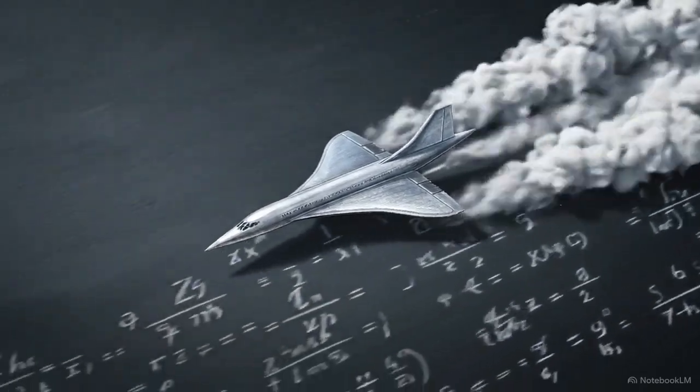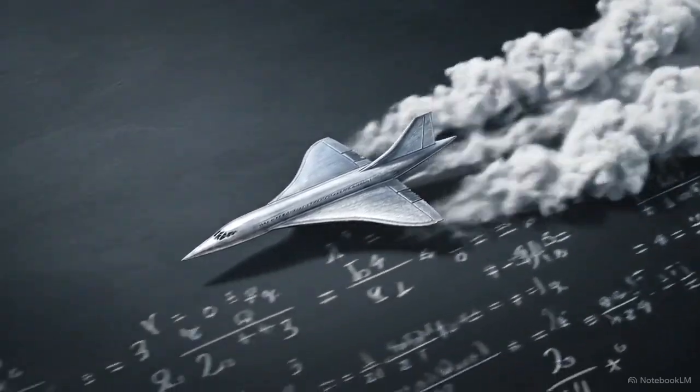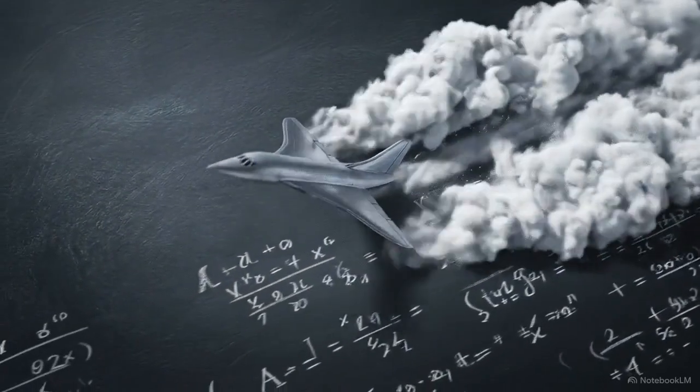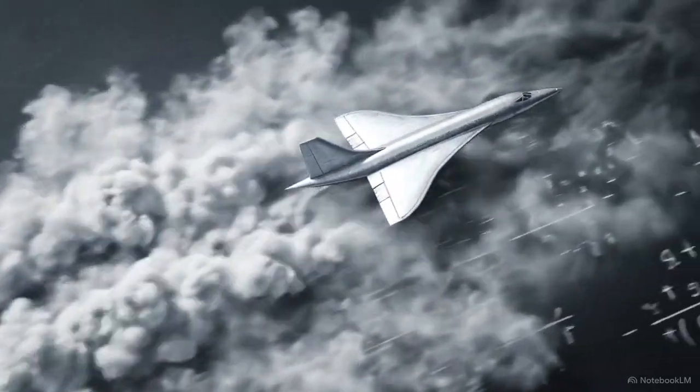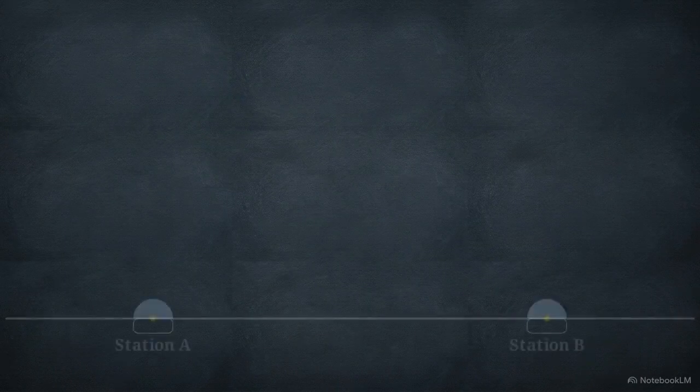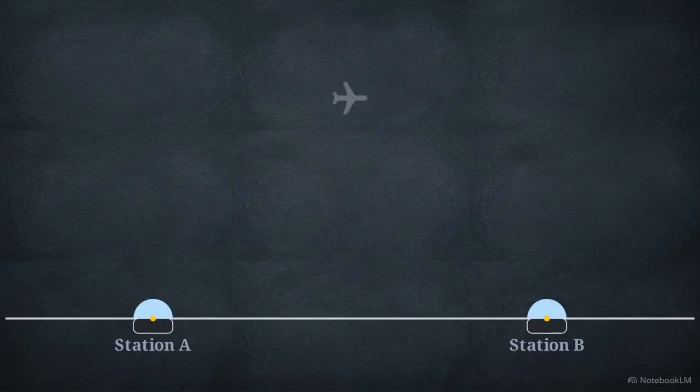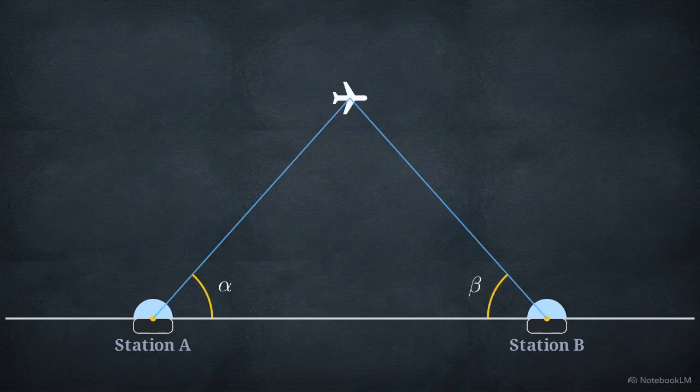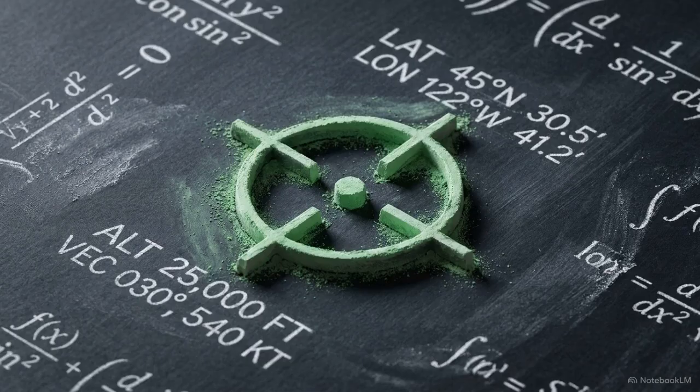Taking this mathematical theory into the physical airspace requires looking closely at how our tracking systems calculate absolute convergence angles. This diagram outlines a standard tracking scenario: two independent ground telemetry stations measuring distinct elevation angles, alpha and beta, to follow a single fixed altitude airframe. To lock onto the target, the avionics computer calculates the absolute convergence angle between these two active radar beams.